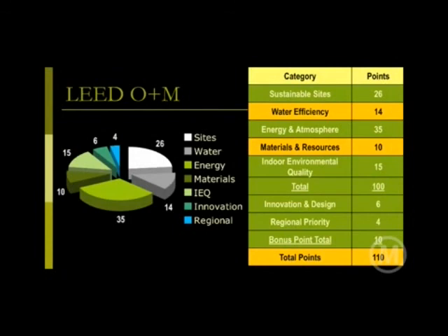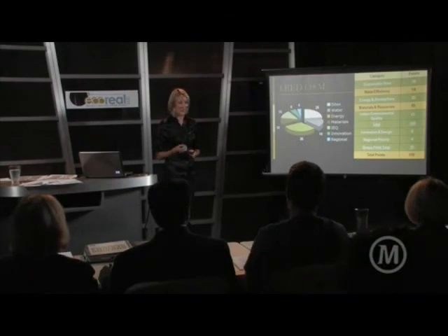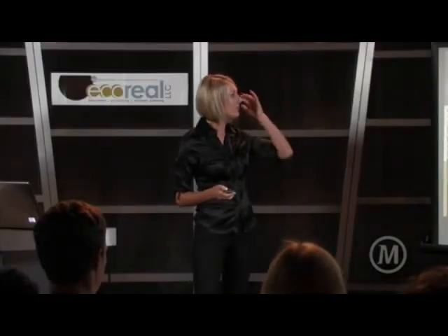Materials went down because maybe you're not switching out materials. Maybe that's deemed a little wasteful, but you are putting an aerator on your sinks, things of that nature, things you can control. Maybe you're switching out toilets because the water savings is worth it. The standard right now is 1.6 gallons per flush, and the old toilets are about double that. So that could be worthwhile for an existing building.